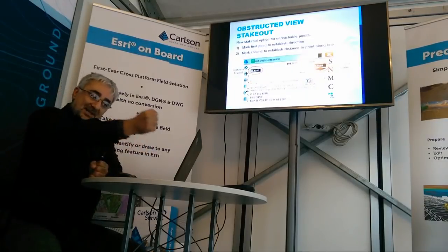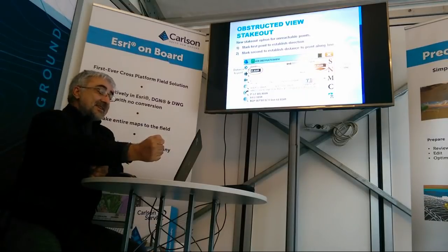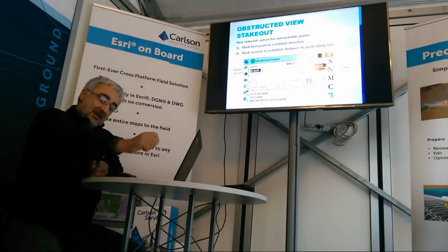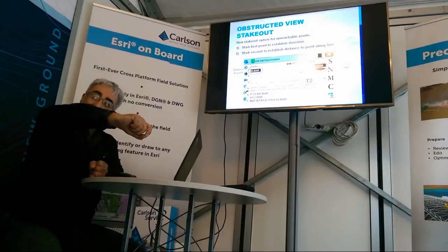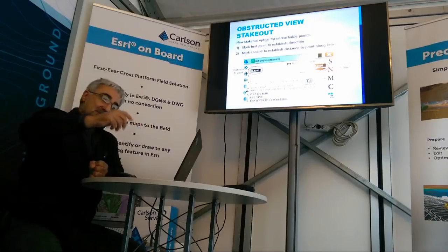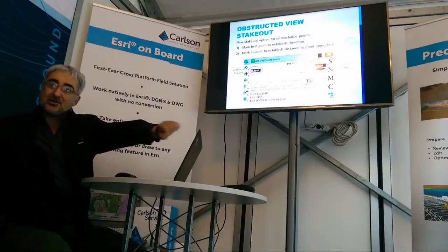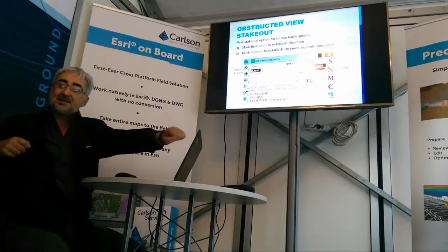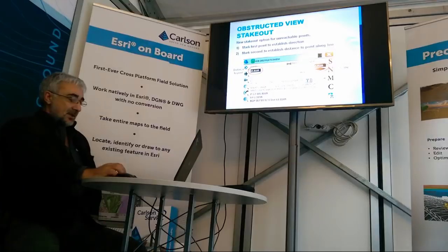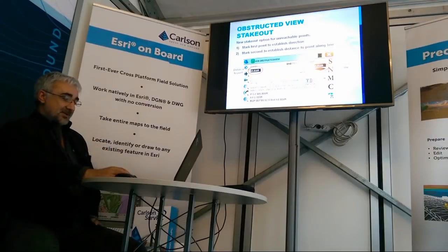And then you put the second stake wherever you want, and you have the distance to the point. So you can put a stake and write with the marker the distance to the point. So maybe you never touch the point, but someone can put a string, measure, and stake out the point anytime, the next day and the next day. So that's here. It is for GPS, for robotics, for everything.